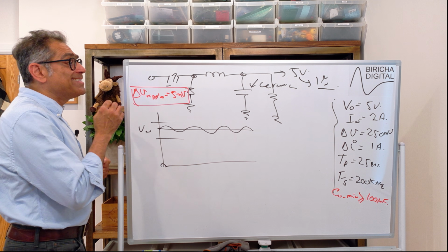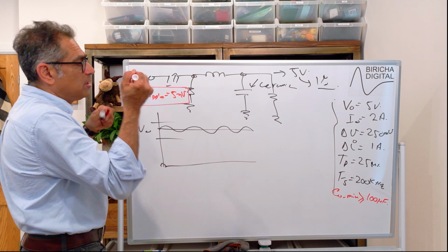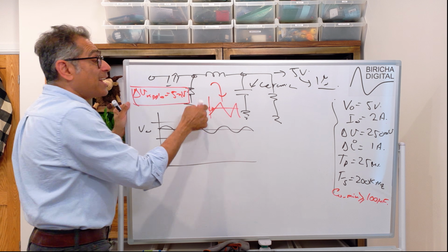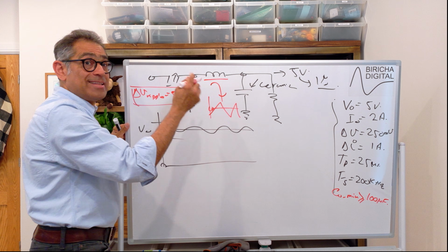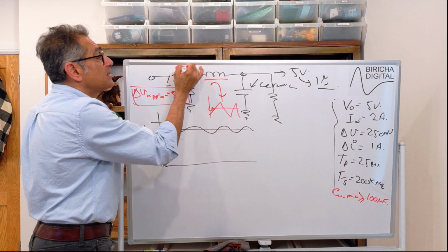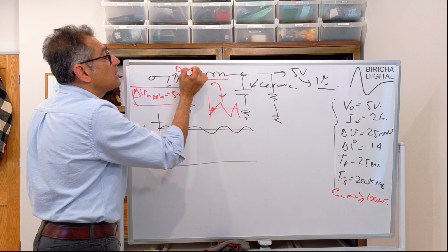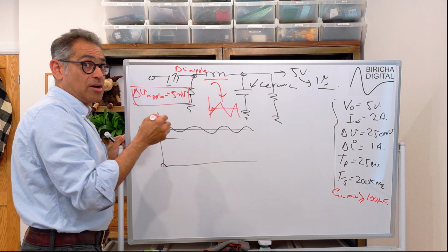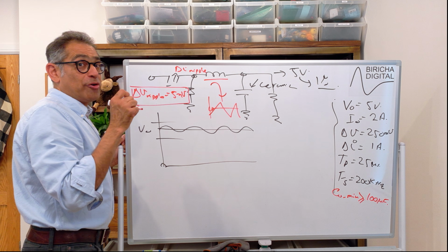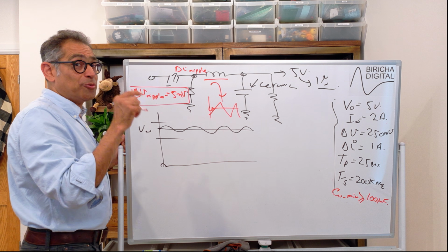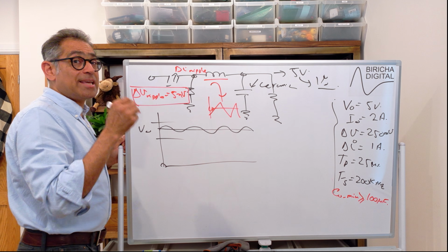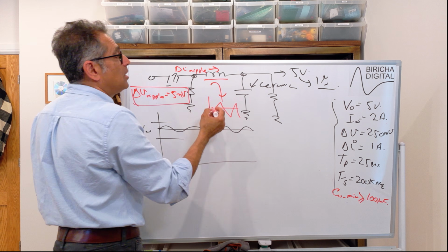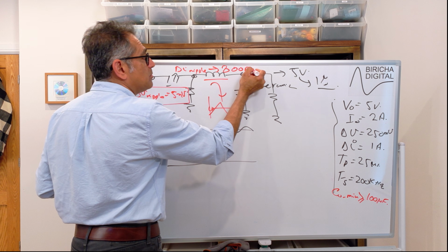I know that the actual ripple current that is going through here, which looks like this, and I know this already because it's the peak-to-peak ripple current of the inductor, delta I ripple. And the inductor was one of the first things that we designed when we designed a power supply. Again, if you're watching on YouTube, there's plenty of material. We've done videos on this already. If you're taking the online workshop, the first thing that we did was calculate this delta I ripple. And let us say that is 800 milliamps, just for simplicity.